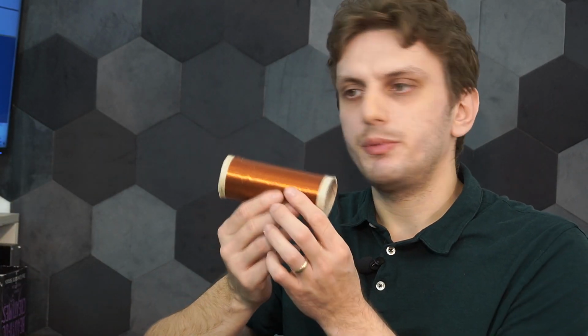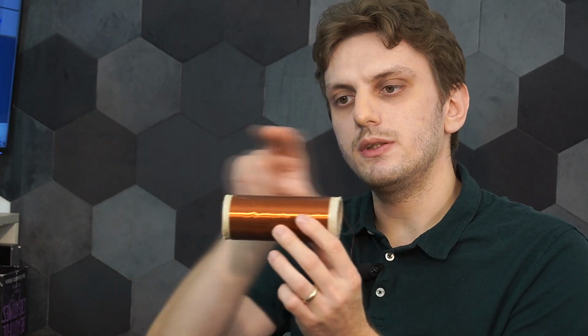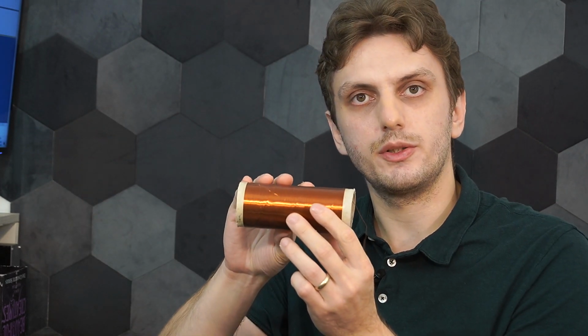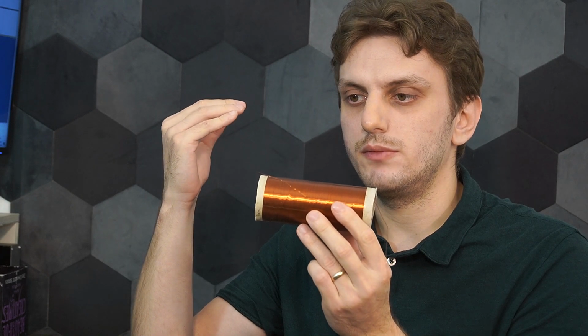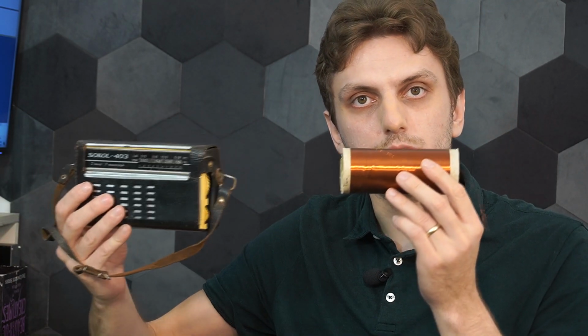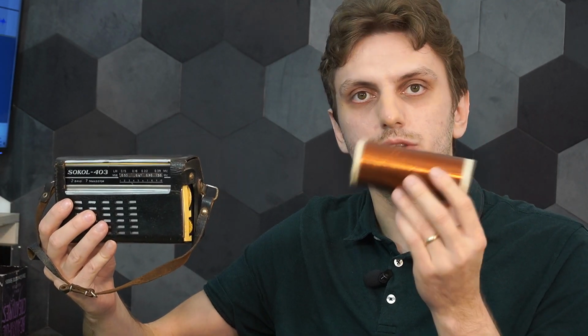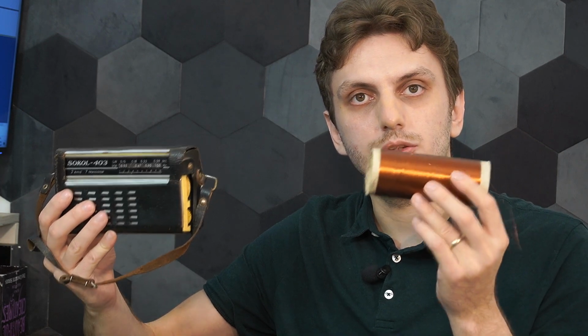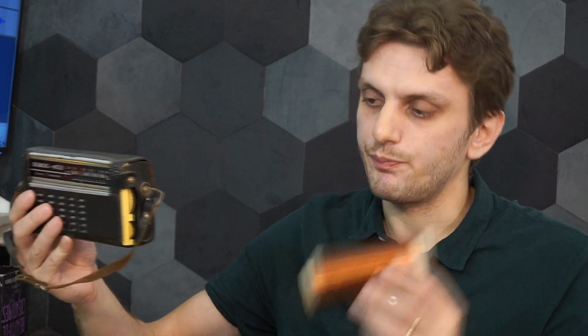For the solenoid shape, you have a very directional field that comes back close to the inductor, and although this should be able to achieve the highest distance, if the inductor and the radio are not perfectly aligned, so if there's any sort of misalignment, then the two will couple very poorly.